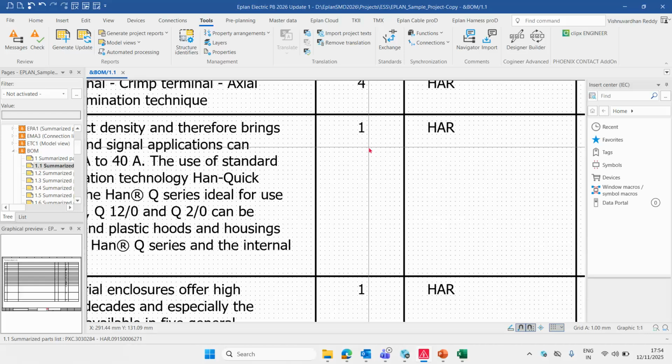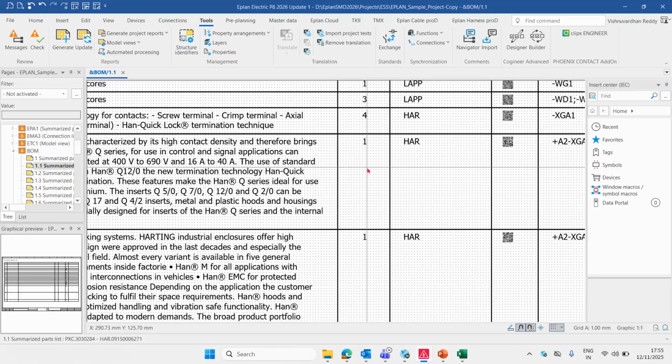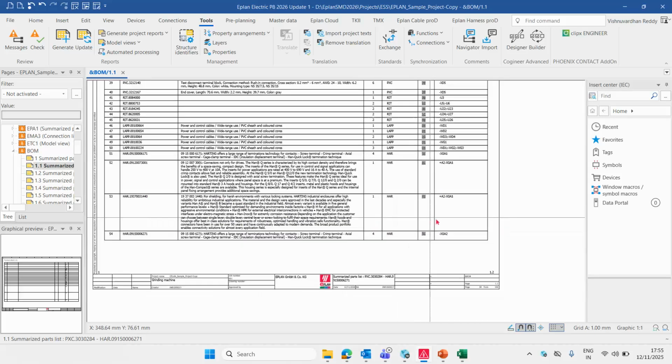But in case you want total length and all those things, in that same configuration we can also add the total length there. If you want to see that, take any sample form of summarized part list; in one parameter you would have seen all three added in the same thing. I just showed you how to add a total amount, but on the same, if you take the second option, property and calculated, there we can add all these three parameters. So this is how the form can be easily done.